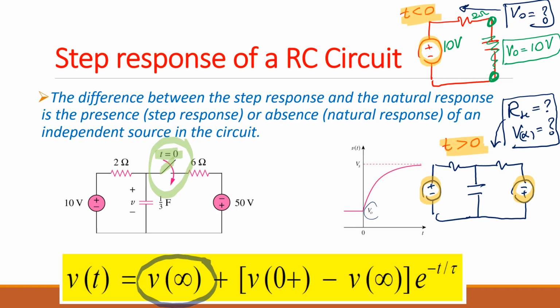Two resistors there, but when the capacitor is fully charged, that path is open circuit. So there is no voltage drop across the two. Am I right? No current means no voltage across the resistor.